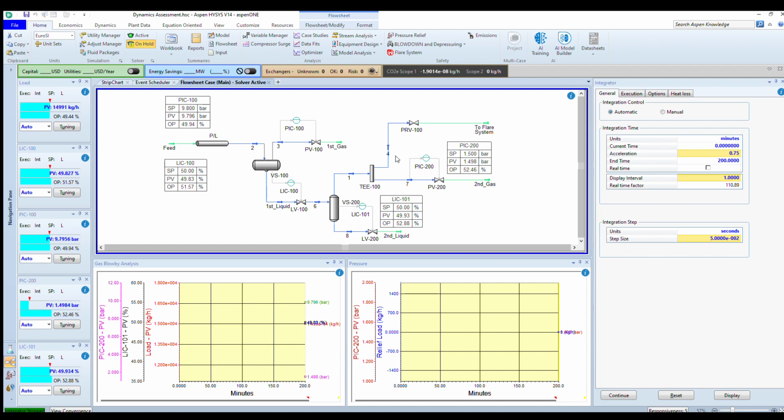And this actually exacerbates the situation, and it puts a huge demand on the LP interface, which means the transient pressure will significantly increase. We will see from dynamic what would be the corresponding relief load and whether this relief load is a close match to the one resulting from the steady state, a little bit more, a little bit less.